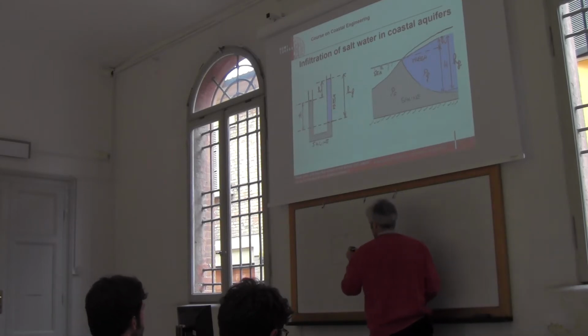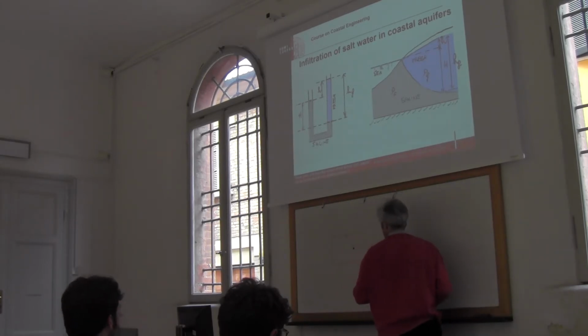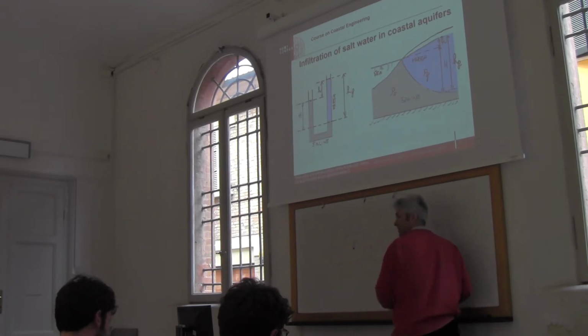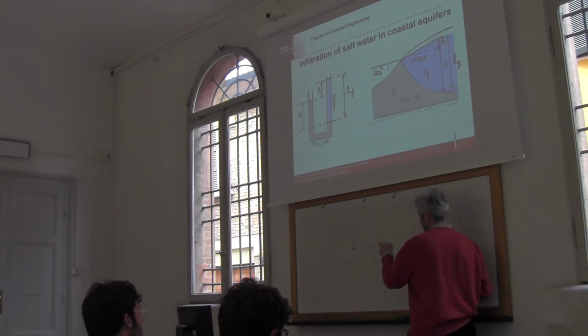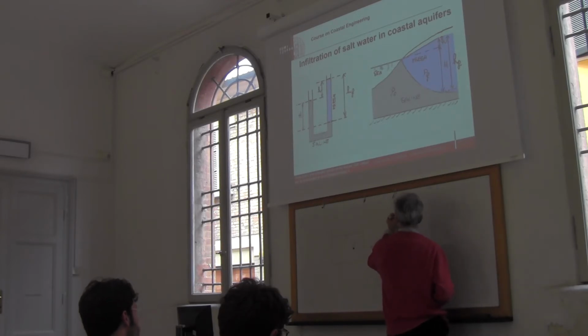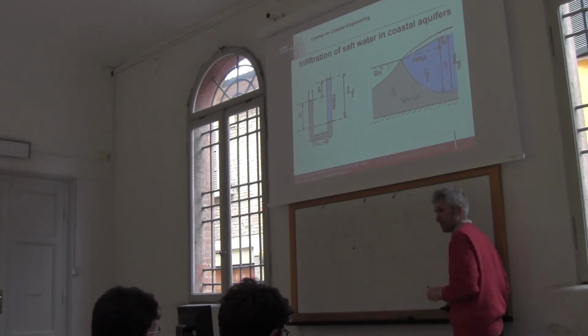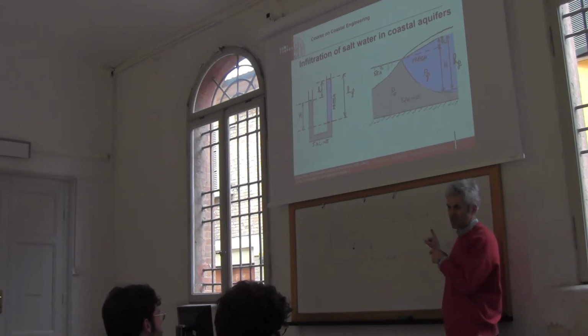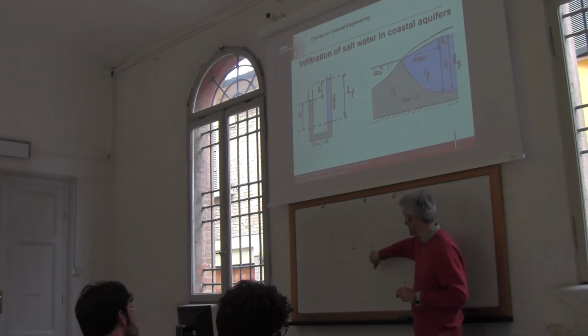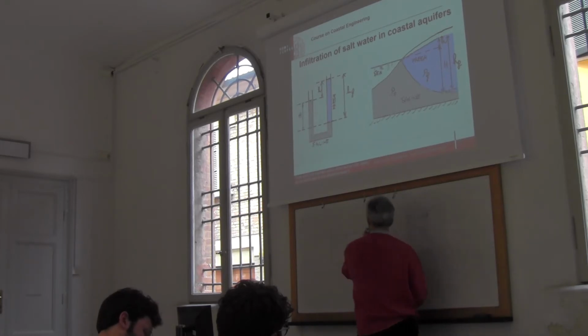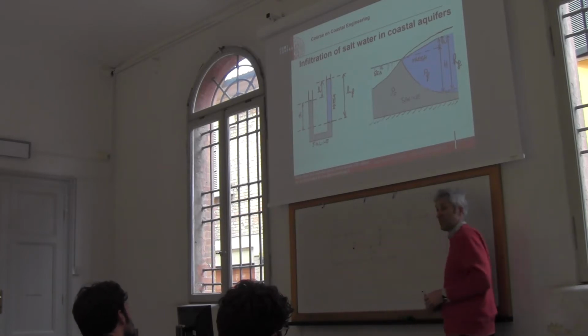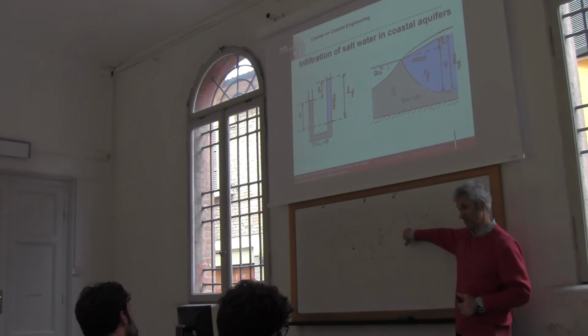On this fluid particle, I have a pressure acting on it, and the pressure is given by the weight of the water column above it. So the hydrostatic law says that z plus p divided by gamma is equal to a constant. So where was the mistake that I made before, that changed my sign? My problem was that I made reference to the quantity H, which has a different sign with respect to z. So this is the way to express the hydrostatic law.